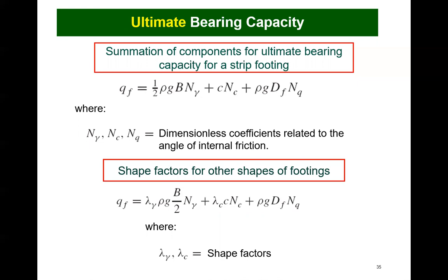It is the cohesion term that is significantly influenced by the matrix suction of the soil. The various bearing capacity coefficients are only dependent on the friction angle for that of a saturated soil. In other words, the bearing capacity factors are not influenced by suction in the soil.